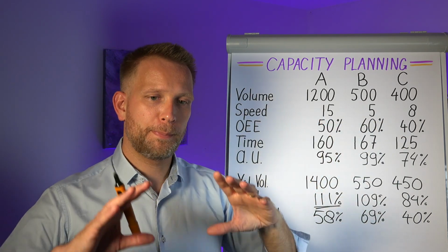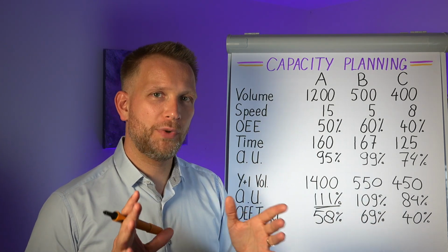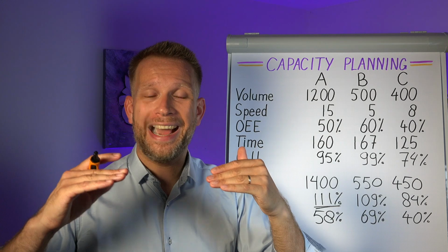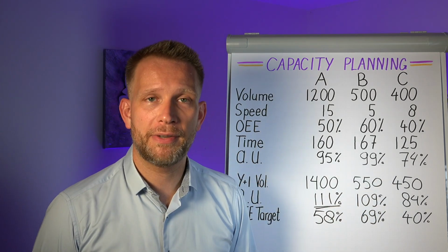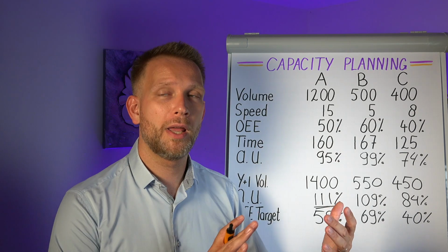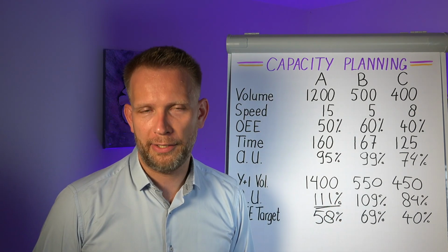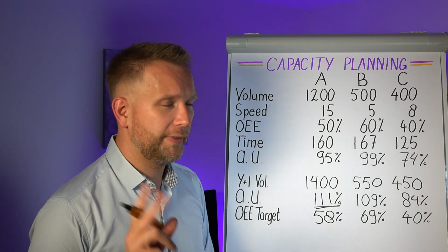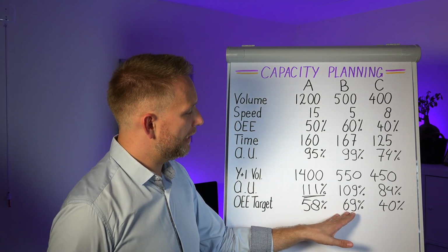If that is all planned types of downtime, and they are very stable, and we need some re-engineering. If there is a lot of up and down, and certain shifts maybe can already work at 70 or 75% OEE, while other shifts cannot, then we know this is going to be relatively easy, very doable within a year at least. You can do a lot within a year if you focus your improvement efforts on a line. So this will give you the target.